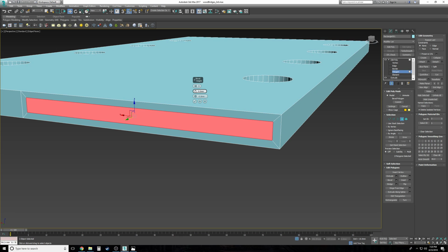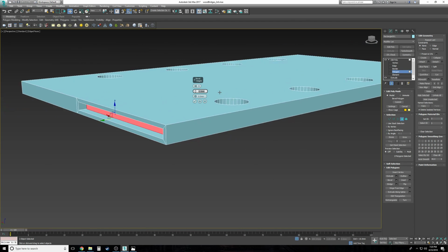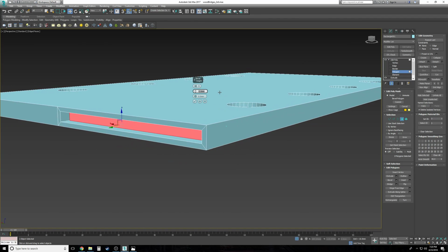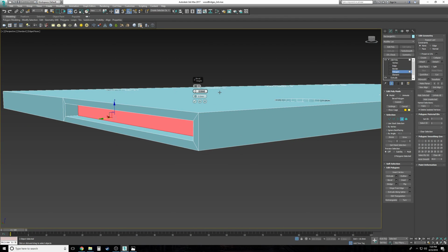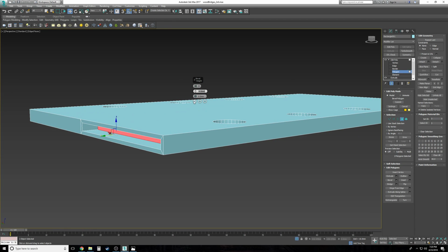0.8. Before you go doing anything like that, push plus. After you've got your bevel down like that, push plus, 0 to back out, and then extrude it inward. And we had it at 0.8, and now we're going to do it 0.2 millimeters. That should be enough. Now let's make it worse than that. Let's make it 0.4 millimeters.